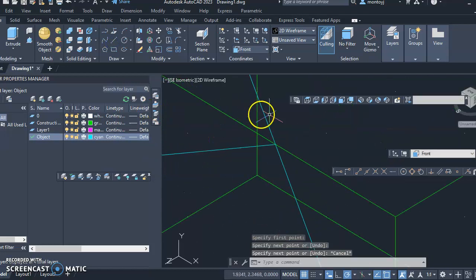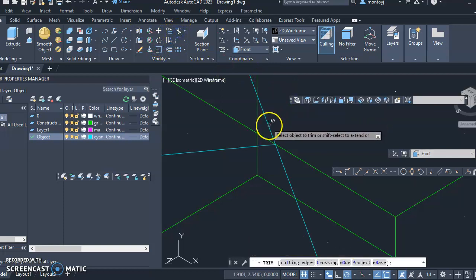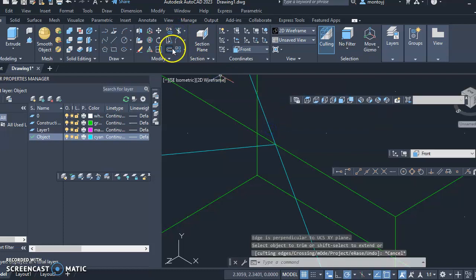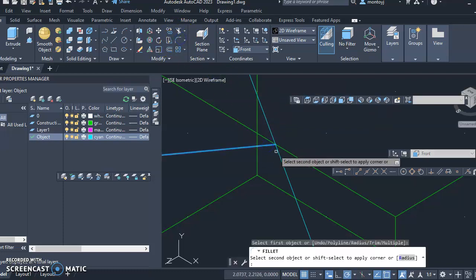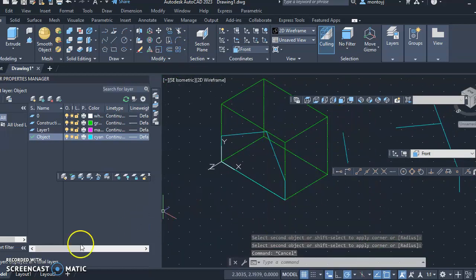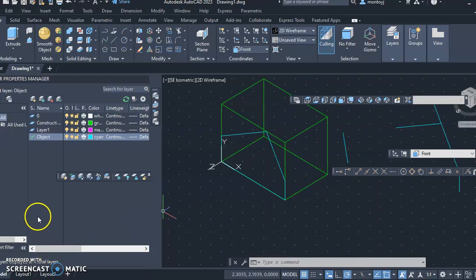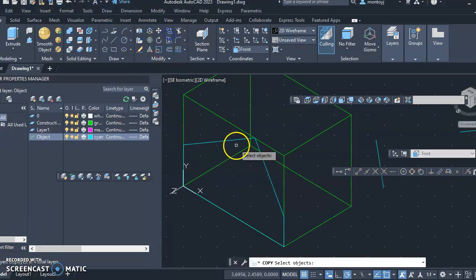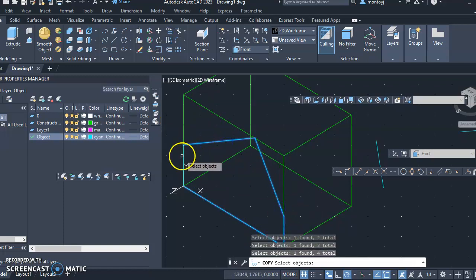I like when I just have to connect dots. Now I can trim. Okay, it won't let me cut that. Let's try fillet with 0. Okay, fillet with a 0. Okay, we have one face that we can use. Now we can use our copy magic. Make sure that we select everything we want to go. There, that defines the shape. Enter.